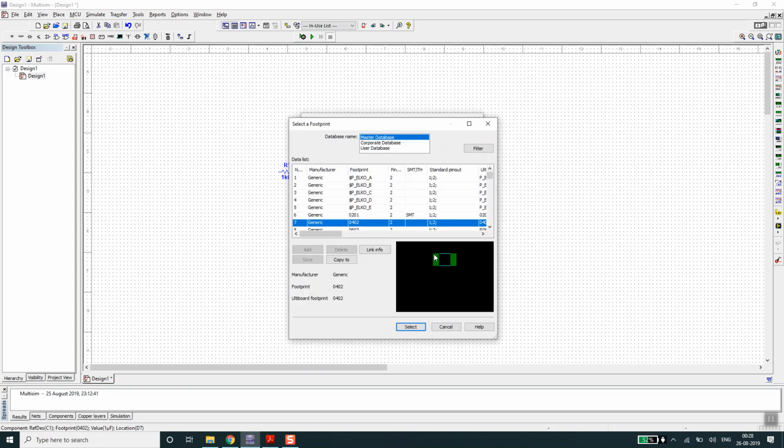So I have to solder this capacitor on this part only. You will see no hole inside this pin. So I will be placing my capacitor on this part. The pin will be soldered here on the top, from the only side where I have placed the capacitor, and I will solder the other pin of the capacitor over here.